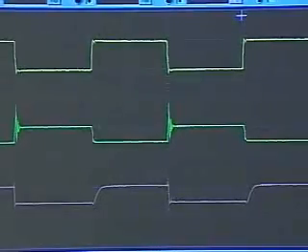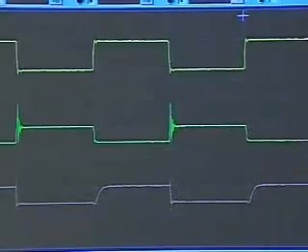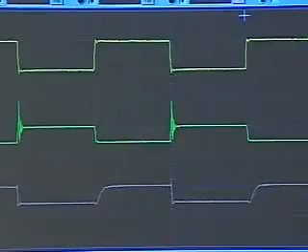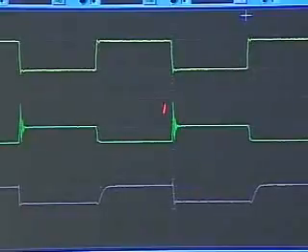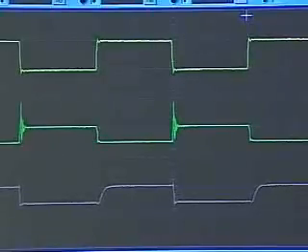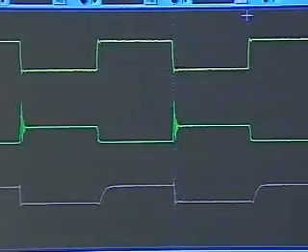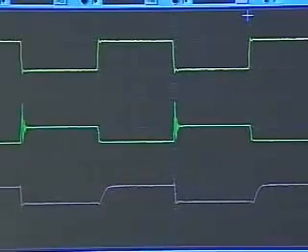I was noticing these sharp lines at all my transitions. Okay, when I looked at my scope, I expected to see nice little square waves, but I saw these nasty spikes sitting out there. And then when I stared at it more carefully, those spikes are really sinusoids that seem to kind of get tired and go away. So those are nasty, those are real, and they happen all the time. And what we'll do today is try to get into that and understand why that's the case. We'll understand how to design that away.